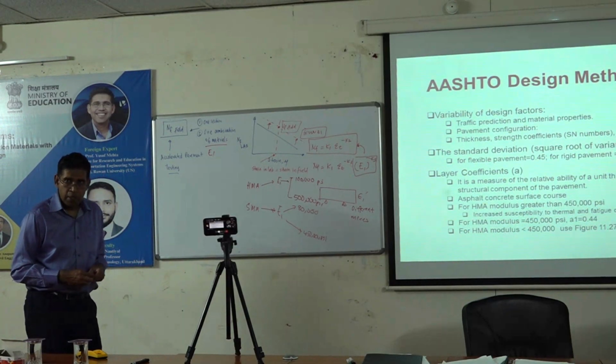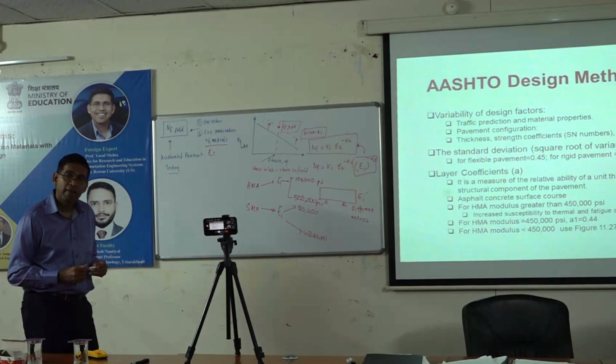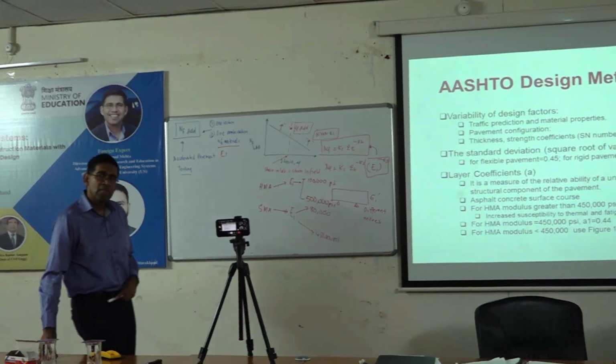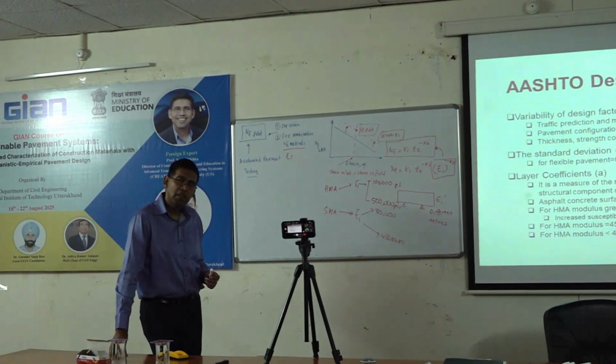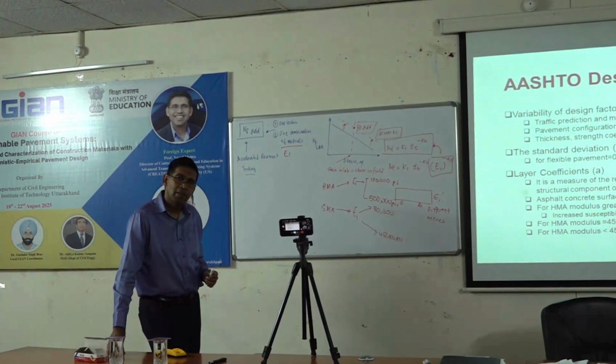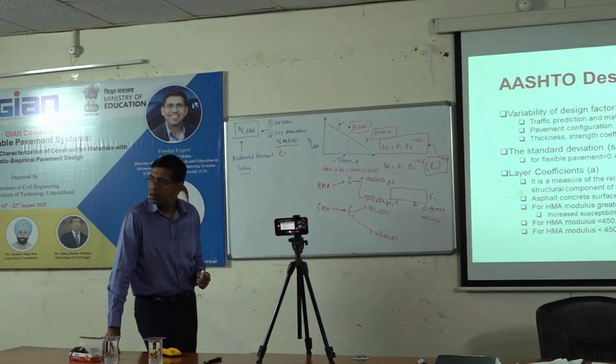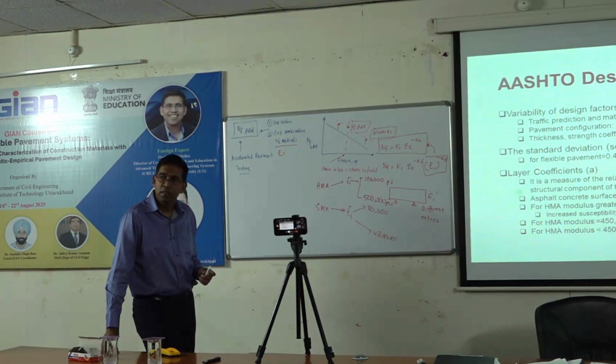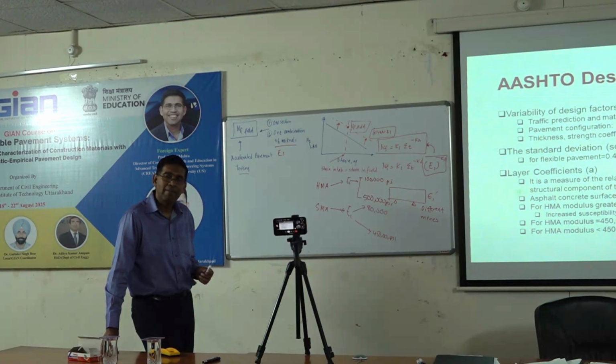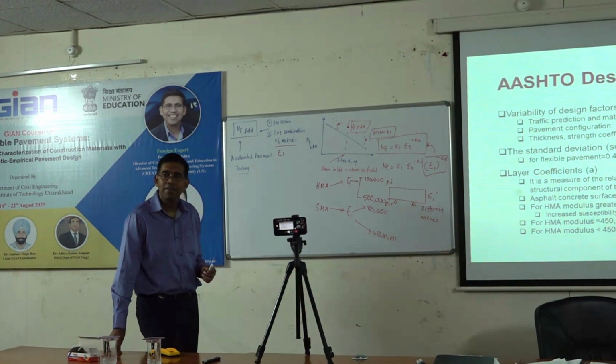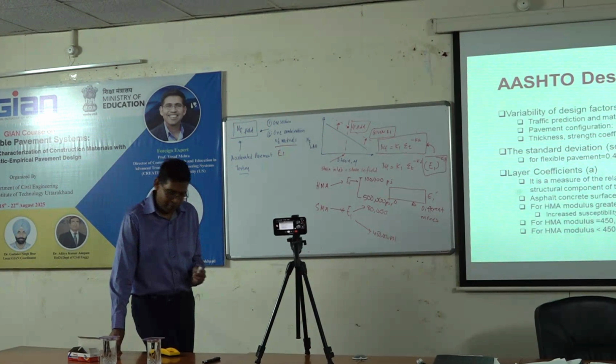Excellent question. The last question is, similarly, the way we have calibrated the lab fatigue equation with respect to the field fatigue data, let us say if we consider any test method like a wheel tracker in the laboratory, it also has some specification criteria and a corresponding number of loading cycles in the laboratory for a particular loading condition. How was this arrived at, and can you give some details in this regard? Very good question.